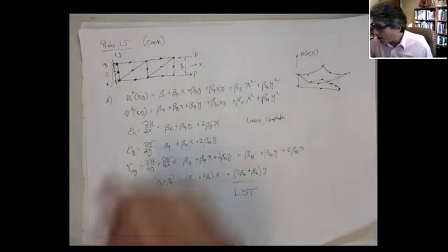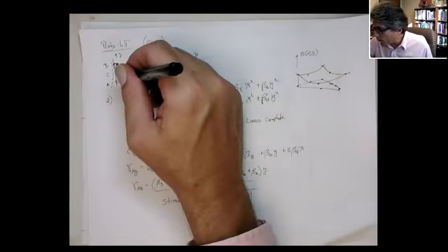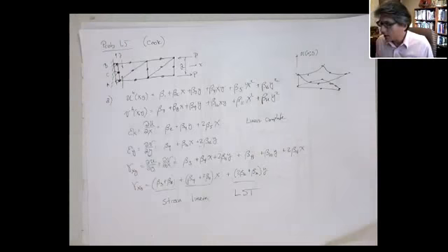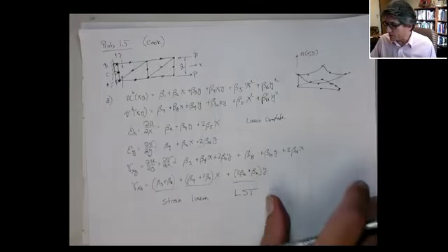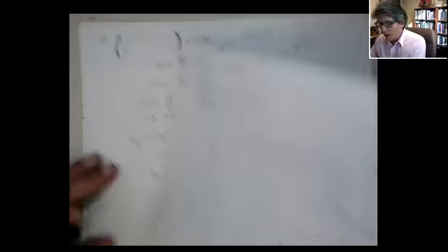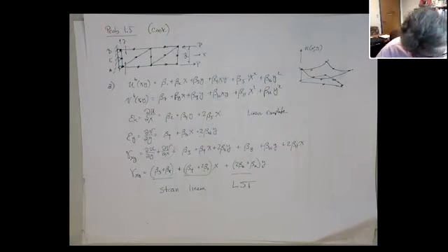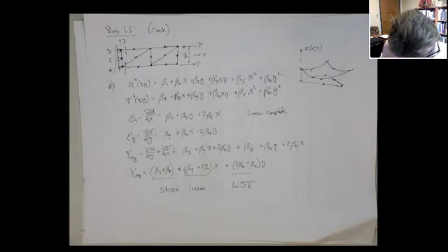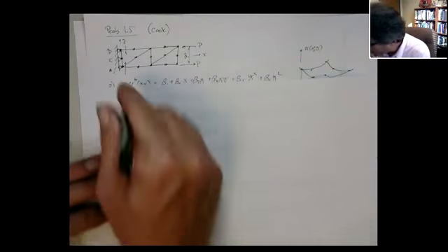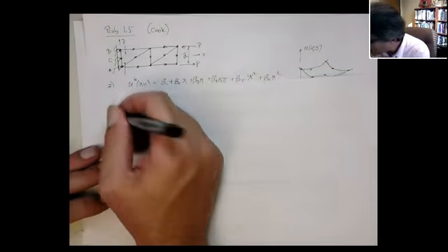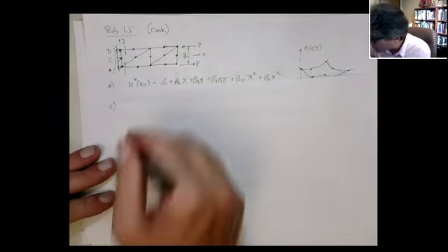Okay. They also ask about the supports in problem B. Why do you pick these supports? Well, again, that is to allow free lateral contraction for a Poisson effect. So that pretty much finished off B. Now, part C asks for an alternate arrangement. Well, really, any type of arrangement that allows free lateral contraction will work.